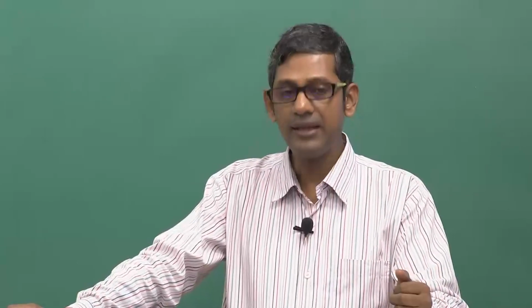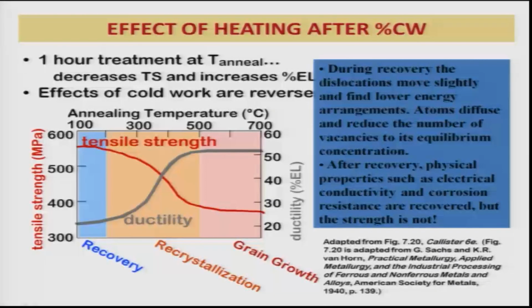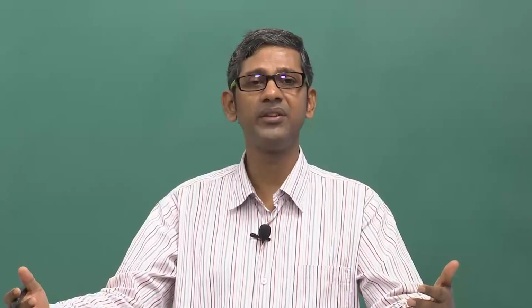We will discuss what is that in a minute's time, and then if you heat further, recrystallization happens. Now recrystallization is formation of the new grains basically, nucleation of the new grains from the deformed grain, and subsequently if heated at a very high temperature, these new grains grow very fast. So therefore cold working of these materials leads to a lot of defects, and these defects actually drive the material for recovery, recrystallization and grain growth kind of structures.